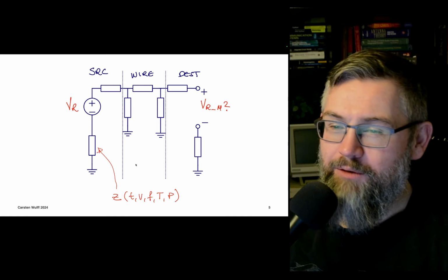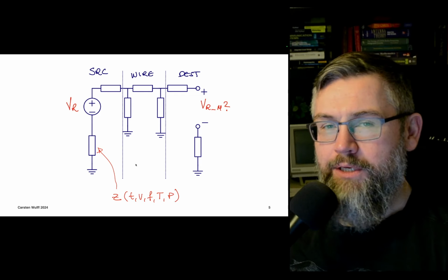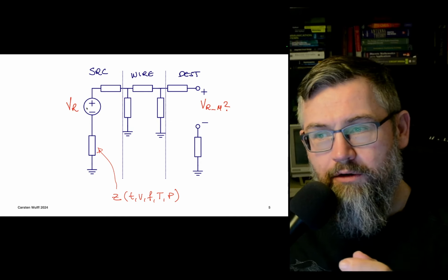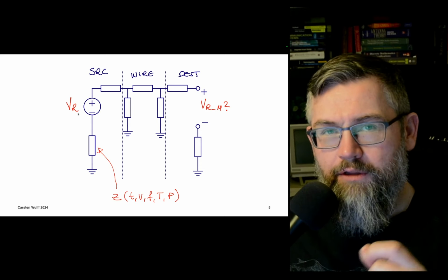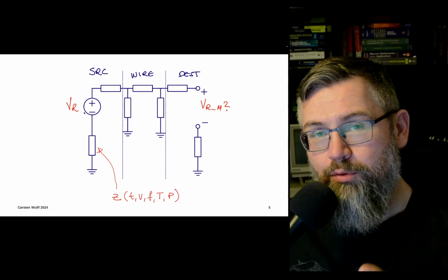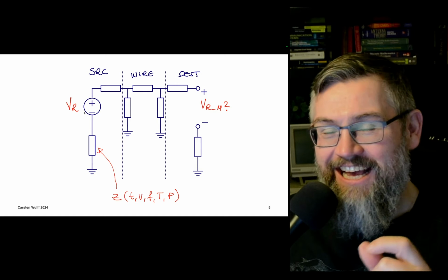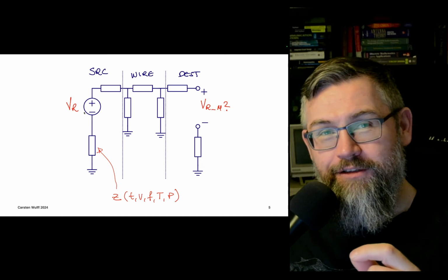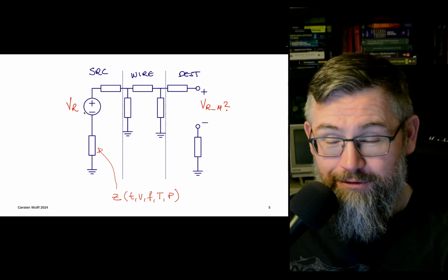Now, one thing that I want to touch on before we proceed with references and bias is that even though we can generate a voltage, in this case VR, internally on the chip, there is still a challenge of distributing that voltage, because as you know, a voltage is really only defined between 2 points. It's not defined in a node. There is no such thing as the voltage in a node. What we mean is always the voltage in this particular node referred to ground is 1.2 volt.